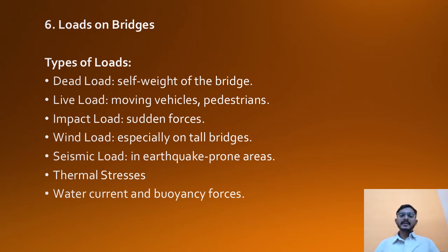Dead load, which means self weight of the bridge. Live load, like moving vehicles or pedestrians, whichever type of bridge is built, whatever is passing, their live load should also be considered. Then impact load, which is like sudden forces acting upon the bridges.